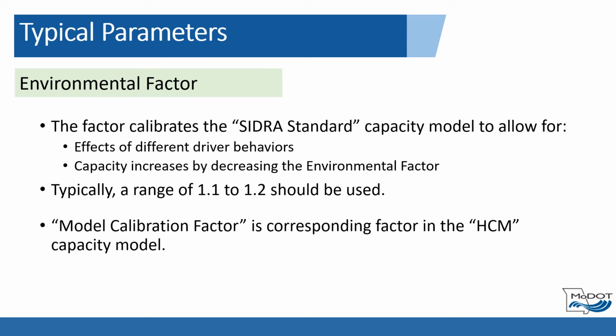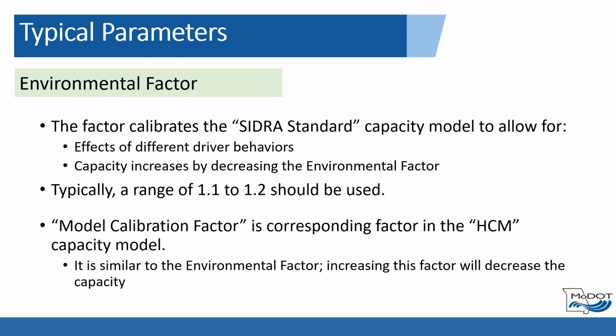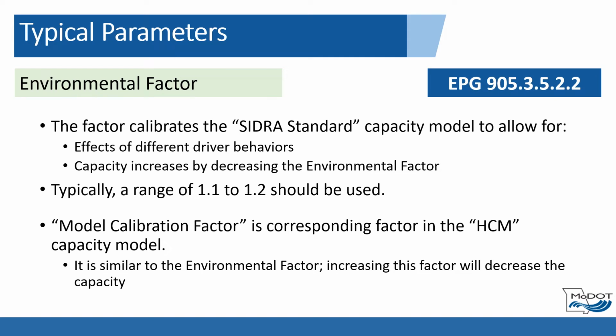The model calibration factor is the corresponding factor to be used in the HCM capacity model. It is similar to the environmental factor, where increasing this factor will decrease the capacity. Refer to MoDOT EPG 905.3.5.2.2 and the SIDRA User's Guide provided with the software for more detailed information.